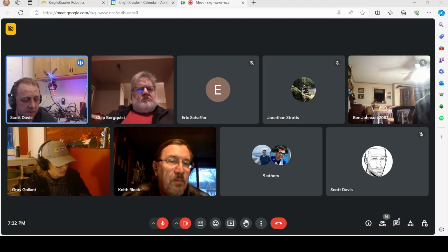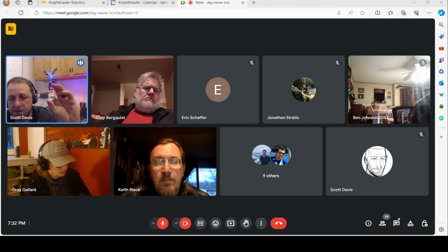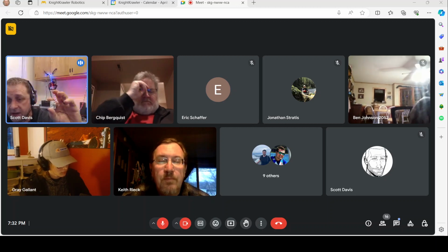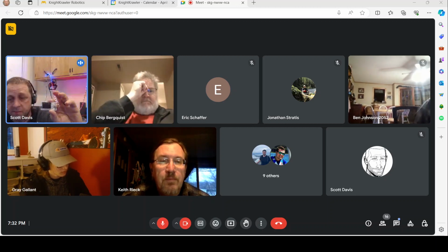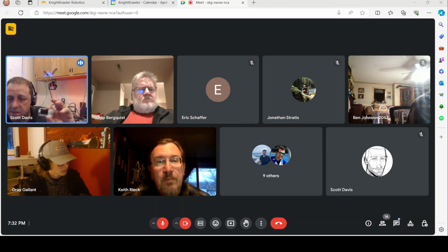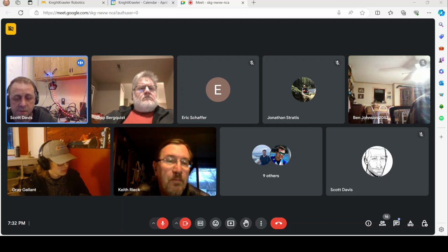What we found we had to do is that when the signal comes in to change the number, let's say that you're showing a 5, which might mean something like I'm aiming, and then you say go to number 6 because you are correctly aligned, it would take as much as half a second to update the display. Half a second is longer than you probably want in order to let your driver know that they can go ahead and fire.